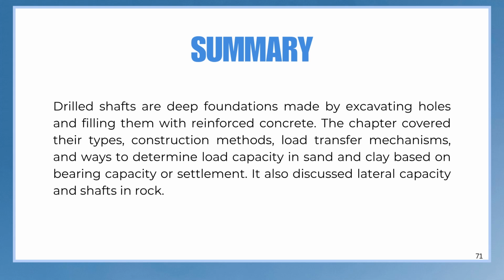Summary: drill shafts are deep foundations made by excavating holes and filling them with reinforced concrete. The chapter covered their types, construction methods, load transfer mechanism, and ways to determine load capacity in sand and clay based on bearing capacity or settlement. It also discussed lateral load capacity and shafts in rock. That's all our report. Thank you.